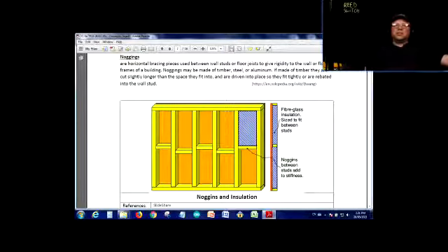Usually those little beaded chains work nice. You just tie it to a string and you just drop it down, and pick it up right at the bottom. Okay, and also when you're dealing in a commercial setting with the steel studding, that's also possible, right? So the installation goes much quicker.